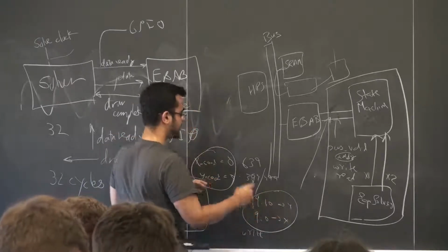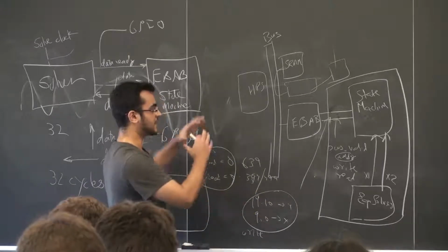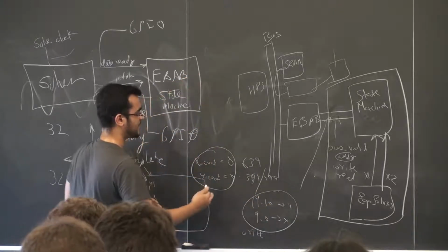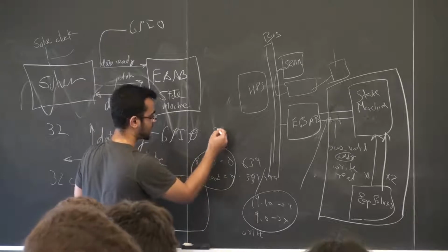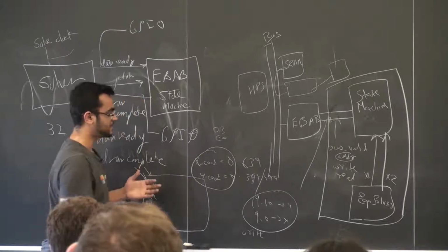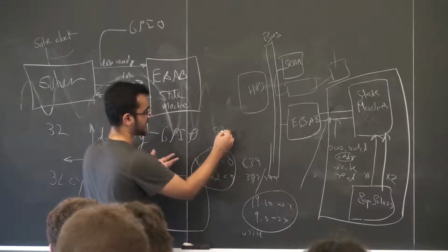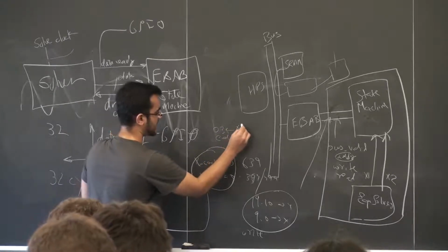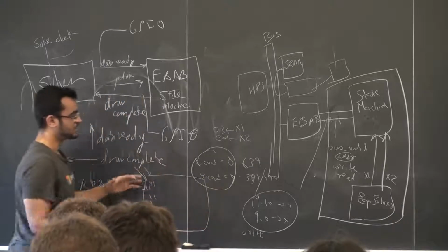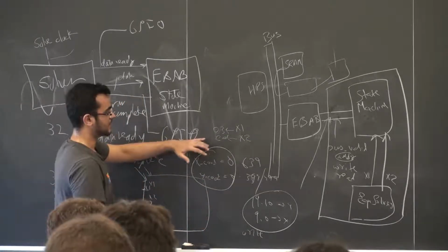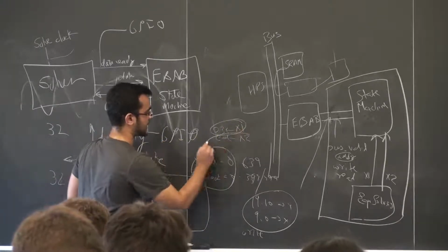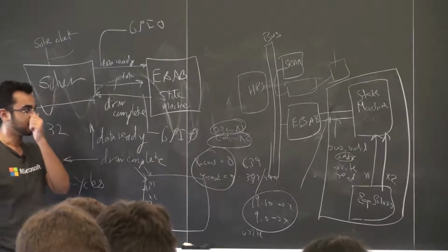If the write data is 0, 0, that means I'm erasing a pixel. If I'm writing 0, 3, then I'm drawing a blue pixel. If I'm writing E0, then I'm writing a red pixel. So for x1 I would write 0, 3, and for x2 I would write E0. Based on my simulation, I would know that I am writing correct values for x1 and x2, and I would go about from there.